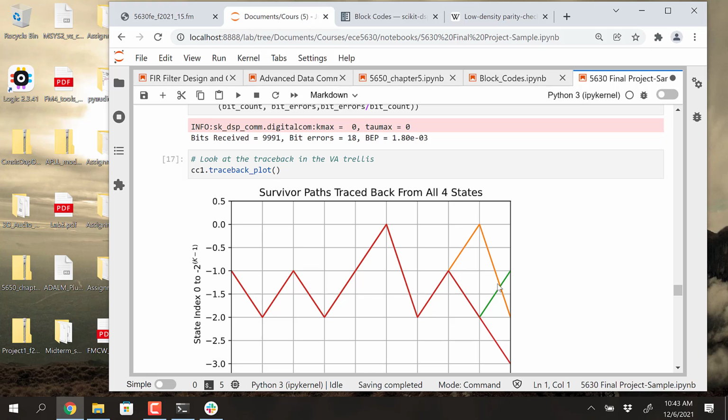It takes longer and longer for it to coalesce as emanating from the same branch. But see, any branch that it emanates from, it can be a 1 or a 0 depending upon the sign in the trellis, right? So that is not good enough to say what was sent. It's the sign. So it could be the one at 0, it could be the one at 1, -2, or -3. They would all carry the same bit that might be decoded out of that, but it's the fact that we've waited long enough with the pruning operation in the trellis decoding to have it emanate from a point of coalescence like that. So we're highly confident. If the decision depth is made shorter, then we're more likely to make an error.